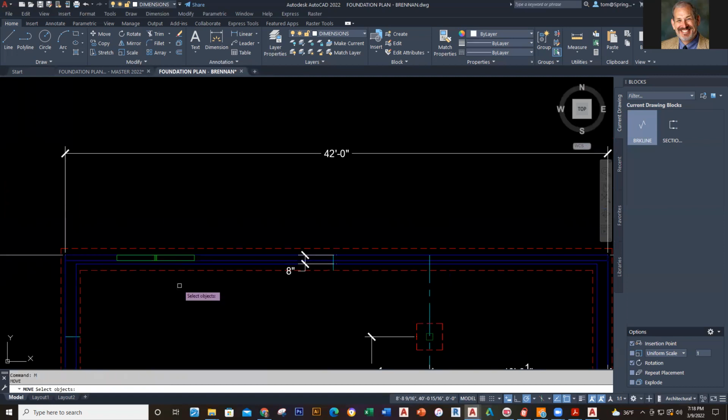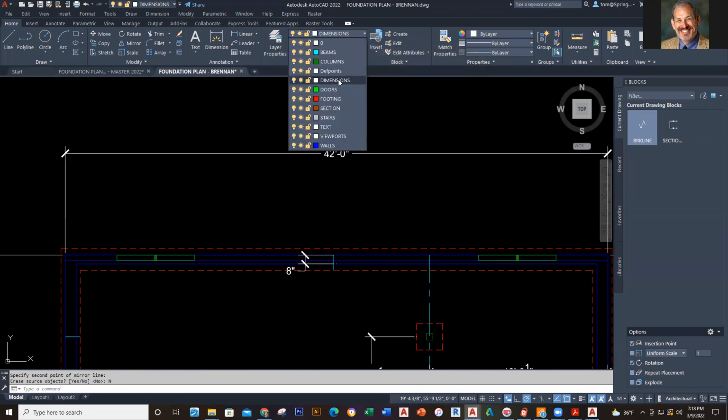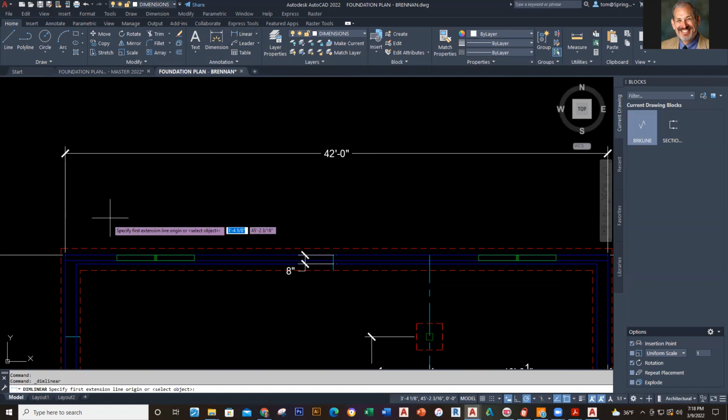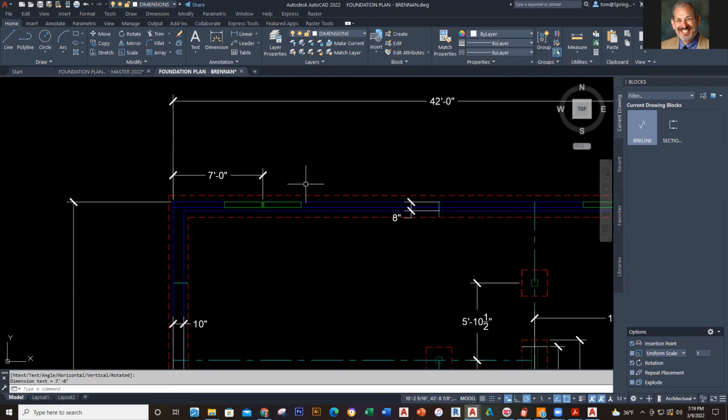And then we can mirror it, because this one actually has to be mirrored all the way over to the other side. So we'll go there, and then the midpoints there, go there. Mirror that, boom, and then the offsets right there, the points there. So we should be there. Now those should be equal from the sides and the dimensions. I'll go ahead and do this just so you guys have this. Go here. Seven feet.